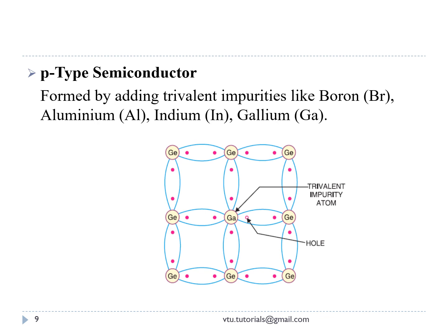These atoms, when added into the semiconductor, form covalent bonding with the germanium, or you can say a semiconductor. So three of the valence electrons of the impurity form covalent bonds with three of the semiconductor atoms.